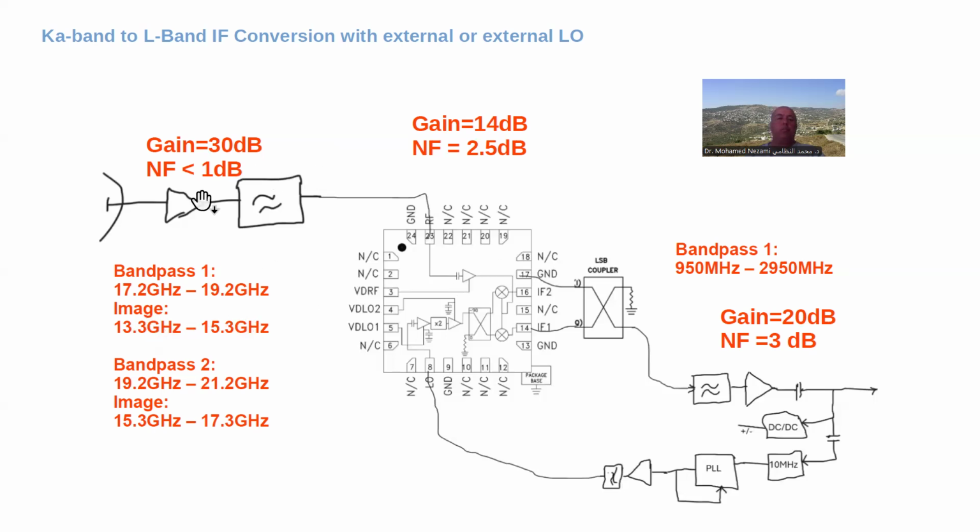So we're going to use an external microstrip filter in here that I'm going to design, which will basically bandpass these bands. These are two different filters. I'm going to switch between two different filters to a common LNA. Of course, the switching is done after the LNA, so it doesn't impact the noise figure, assuming this is a gain of 30 dB, like I have it in here.